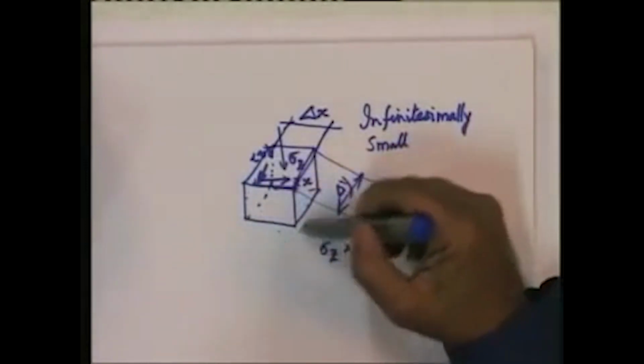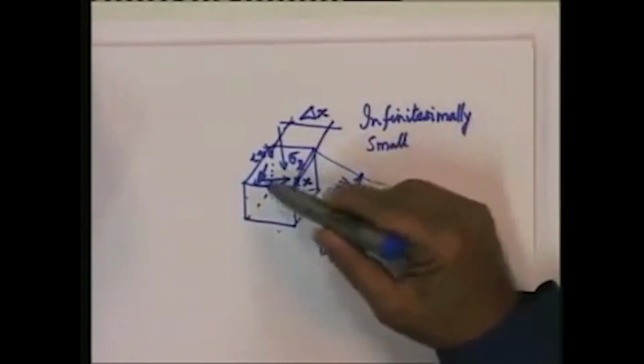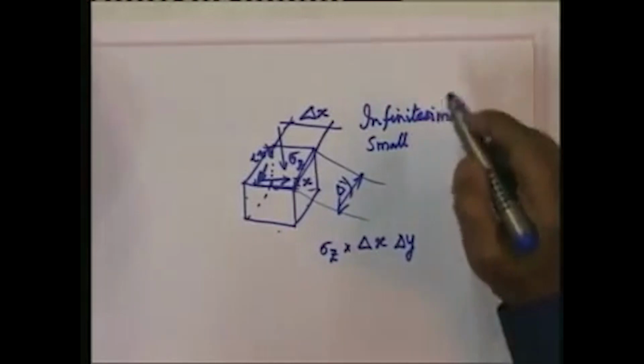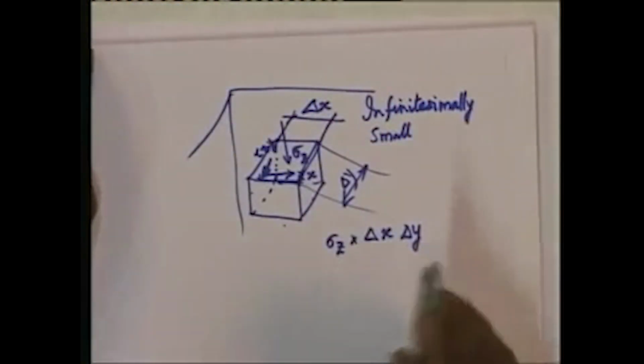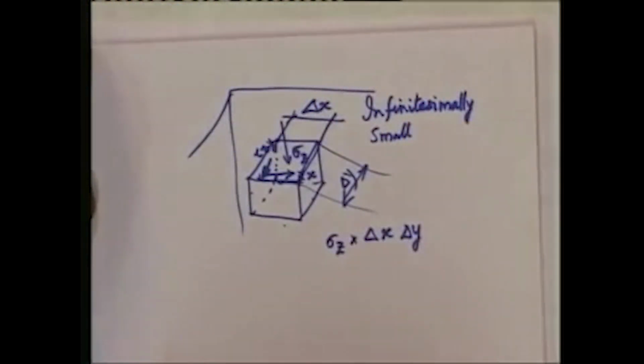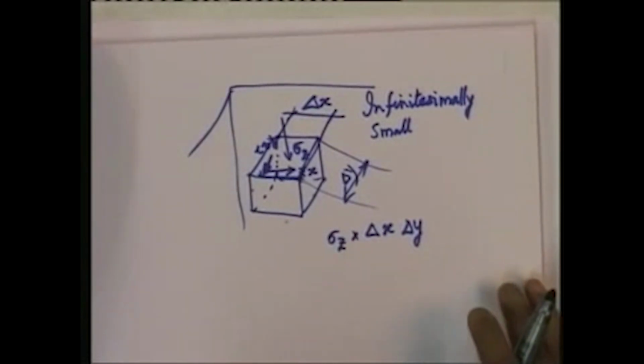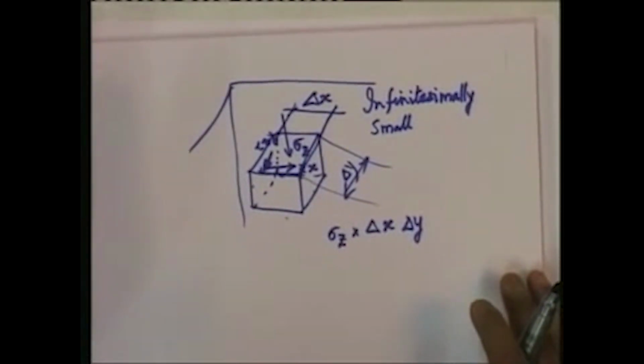Similarly, there will be forces acting on each one of these 6 surfaces of this element. Now, it is very important that this element be kept in equilibrium by these forces. So, what could be better than simply writing equations of equilibrium for all those forces which are acting on the various surfaces of this element. What could be the equations of equilibrium for a 3-dimensional problem like this? There could be 6 equations of equilibrium, 3 for force equilibrium and 3 for moment equilibrium.